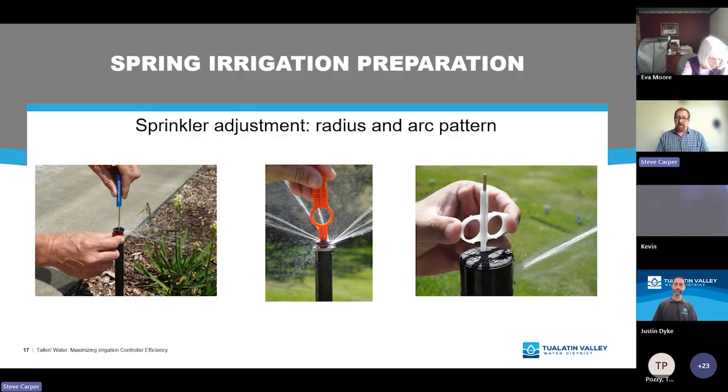So making sure that you've got that proper pressure reduction on the electronic valve assembly for that zone is important. And sometimes, there are retrofits that come out of a sprinkler head. So again, if you find yourself maintaining it more often than is convenient, you might want to consider either replacing that equipment or reevaluating the design.